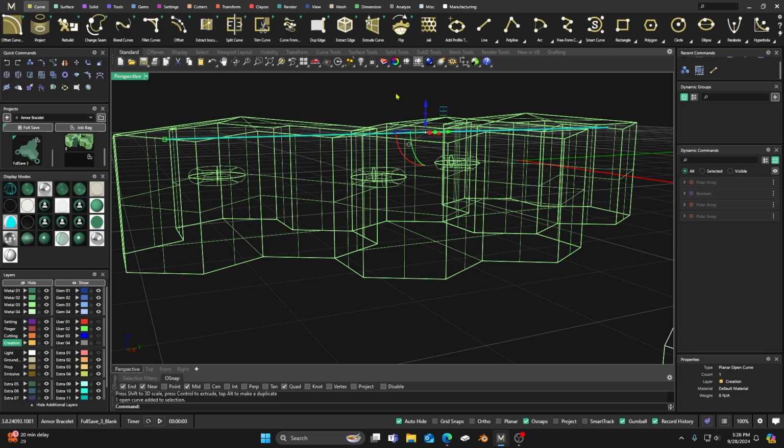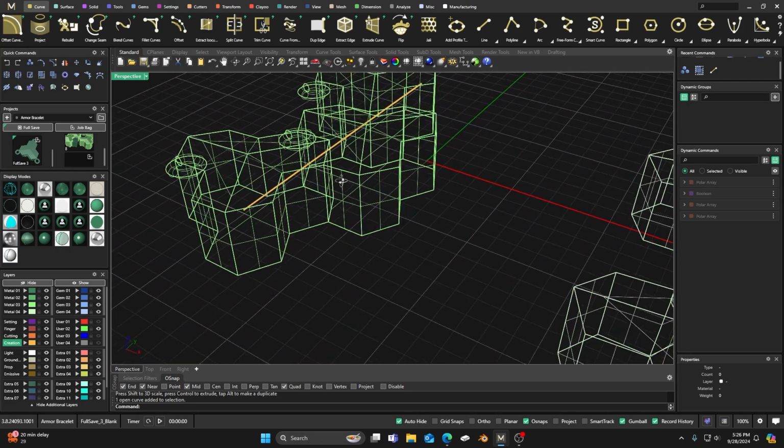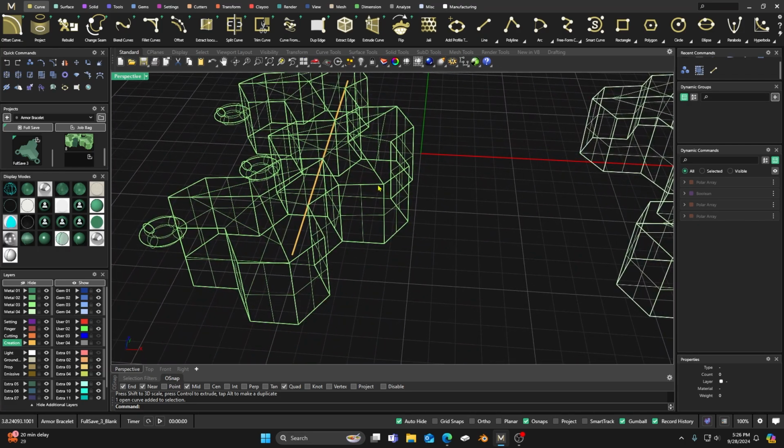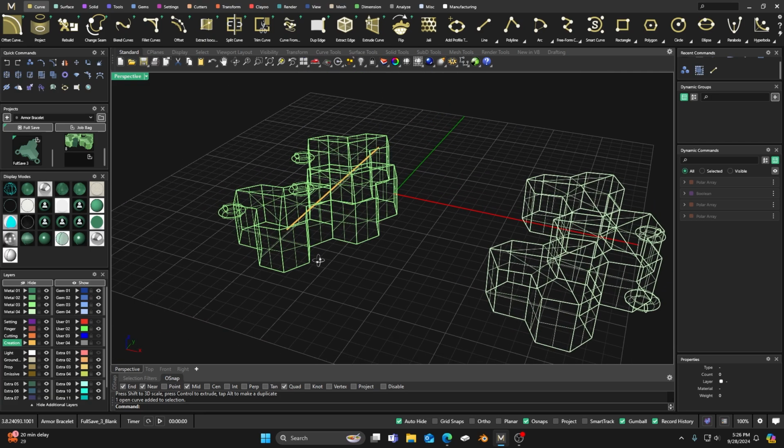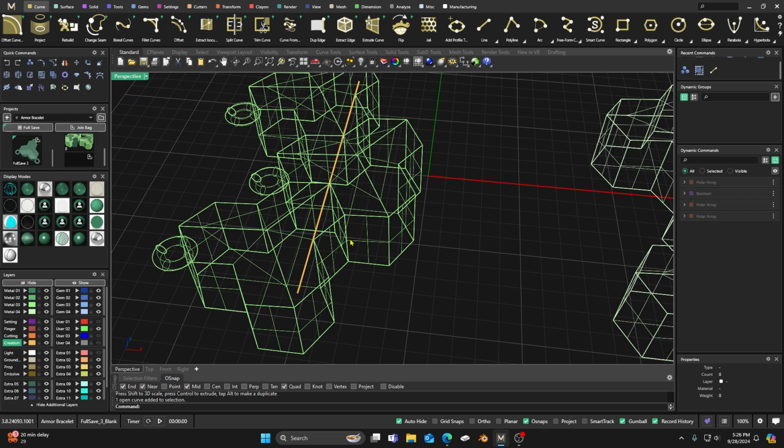So I'm going to select that line, I'm going to click on it, and I'm going to drop it down to at least a negative 0.6 with the shrinkage and everything. I think that may be okay. So something like that, right? All right, and now we need to drag that line out over to this edge right here. So what's the best way to do that?